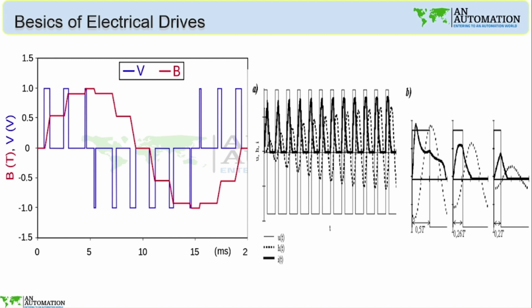So we have to use separate drive duty induction motors for drive purposes. There are many companies who manufacture these types of motors, which are separately designed for drive duty purposes, and if it is not a drive duty motor, then the motor can be burned or damaged because of this. Okay, so this is the square wave.